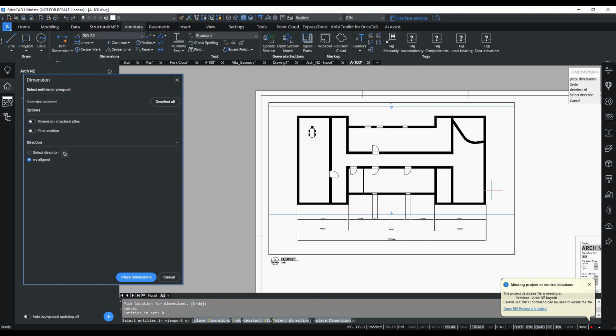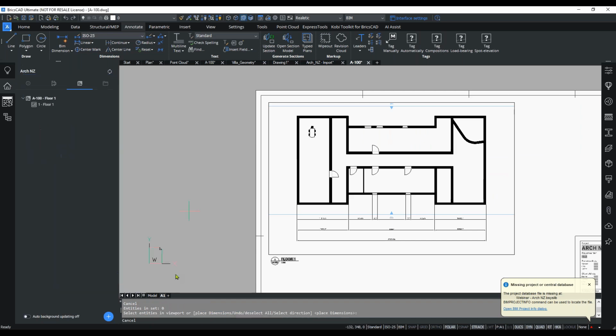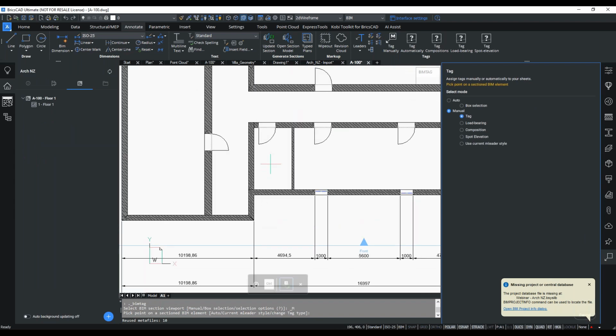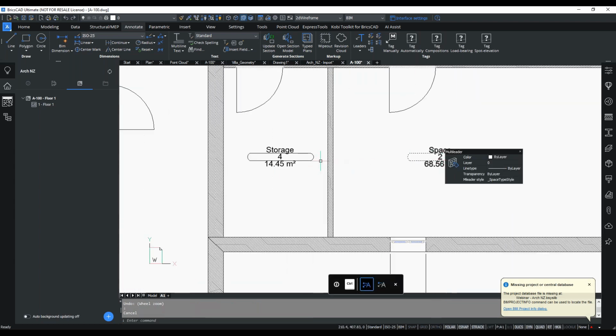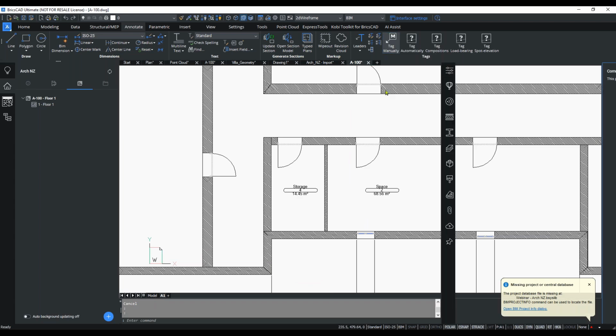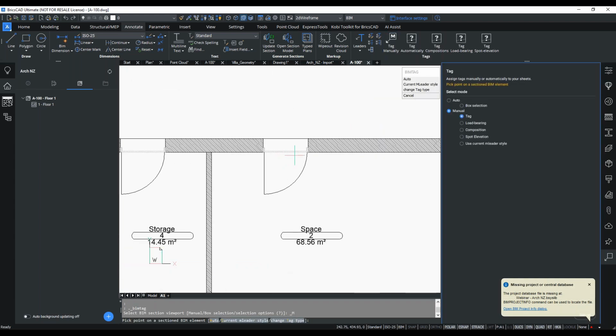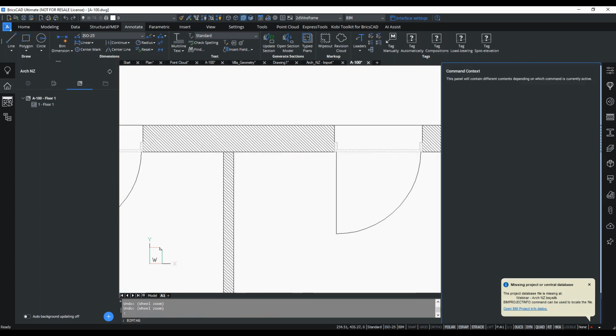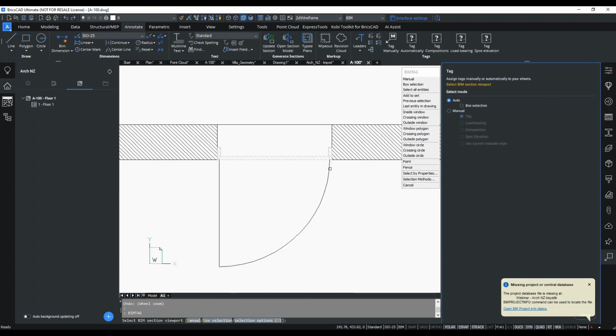What we can also do is label those spaces. Let's go up here to our manual tags and call this space here storage. You can see how that one shows up. This one didn't have a name yet, it was called just basic space. We can also label the doors and windows. Depending on what information is stored on the doors, if you click on these, oh sorry, that was a space. Let's zoom in and make sure we click on the actual door.